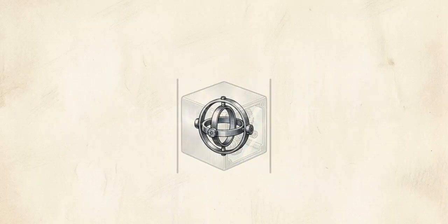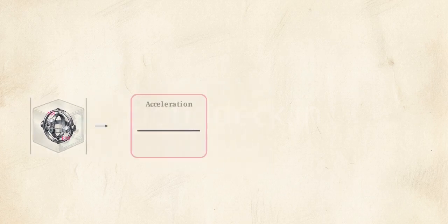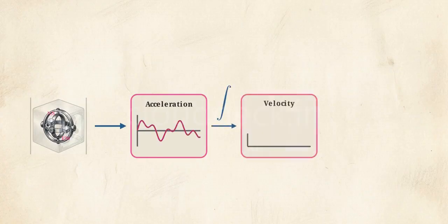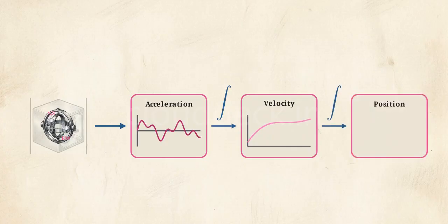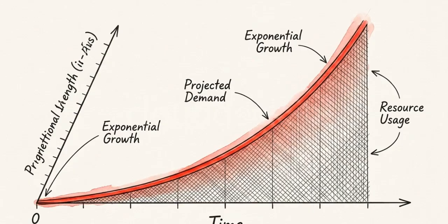Instead of looking outside, it uses internal accelerometers mounted on a gyro-stabilized platform to measure physical movement along the north-south and east-west axes. The onboard computer integrates that acceleration data over time to determine velocity. It then integrates that velocity over time to determine the exact distance flown and the precise geographic position. The system has one initial flaw. Tiny gravity measurement errors by the accelerometers will rapidly compound, accumulating infinitely over the duration of a long flight.